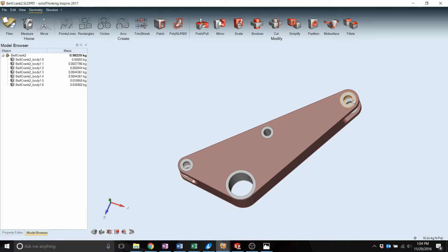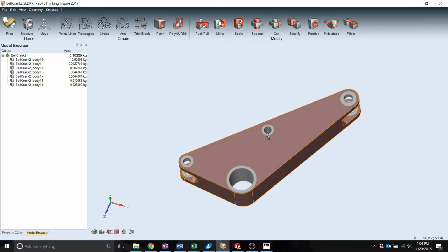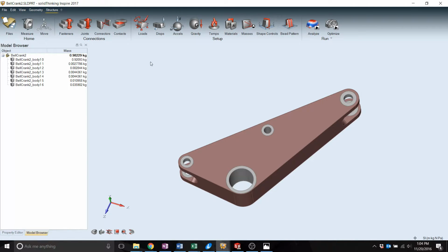Then by default, the other spaces maintain the non-design space characteristic. There are two main tabs up here. This is where you'd model your part, but we're not going to be focusing on that. So we're going to go to the structure side, where you have your constraints and setup, and then your actual optimization parameters.